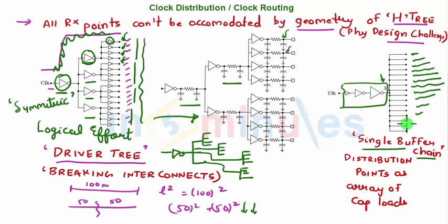And that's the reason these days we have also heard about something called an asynchronous system. Asynchronous systems means something which does not depend on clock. We have already seen this, where you have this control signal which is coming out, and at the same time this control signal might be given to your logic block, which will have inputs and outputs. So your control signal will ask the circuit, are you ready, by sending a request. Once the circuit is ready and gives its output, it will give an acknowledgement. This is nothing but the concept of handshaking, which we have already studied, in which you don't have to be dependent on clock, because right from generating the clock to stabilizing the clock to distributing the clock at different receiver points, it's quite a challenging task.